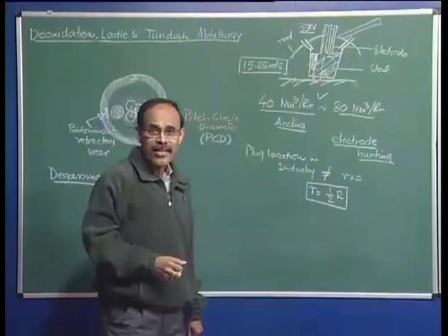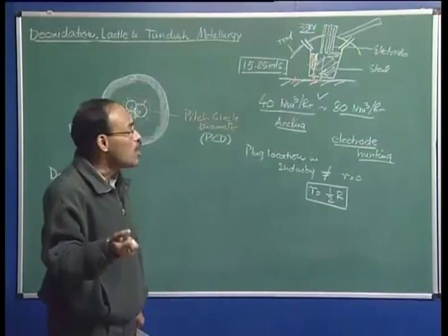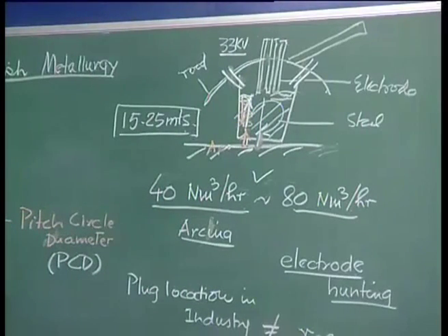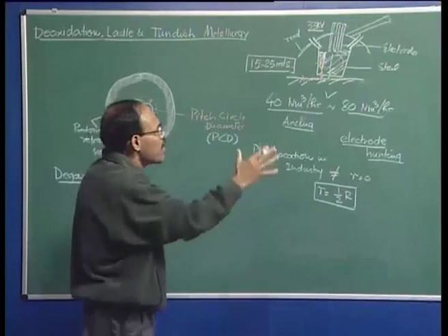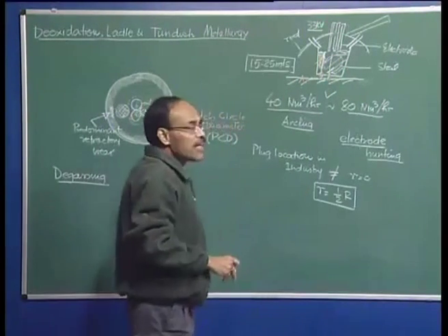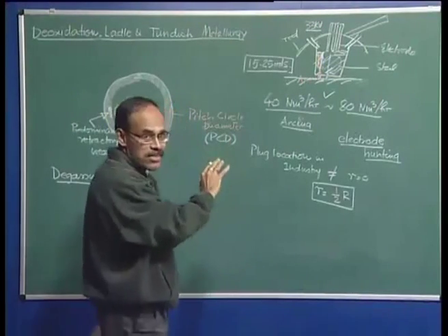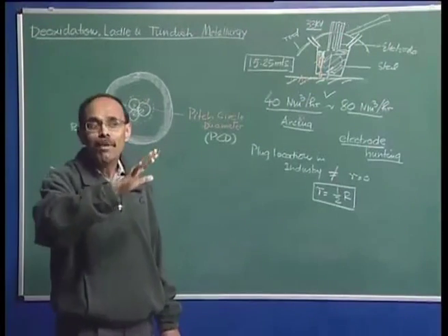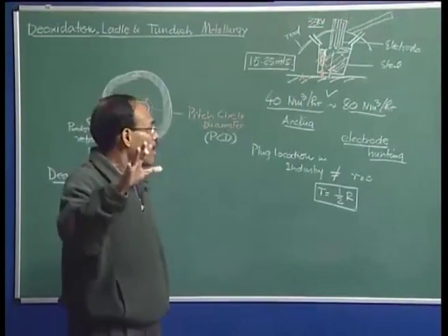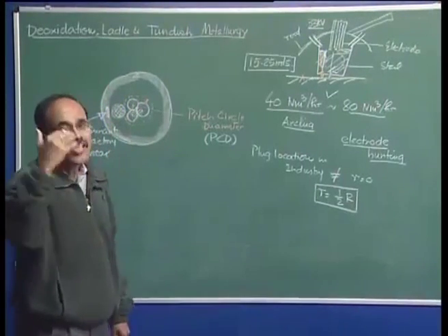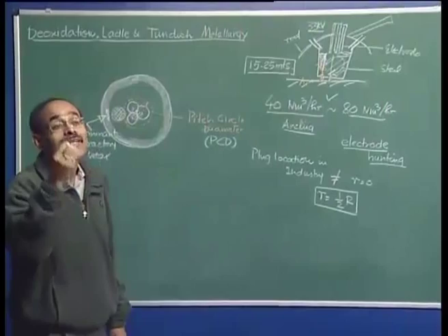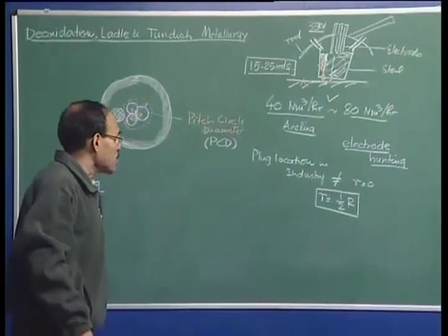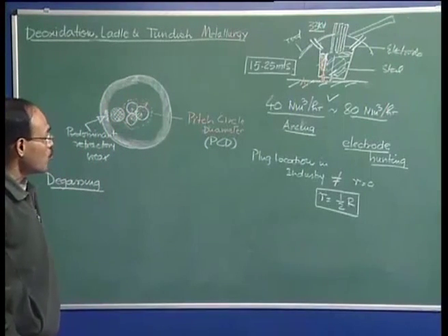The lime may be hygroscopic in nature, being hygroscopic it can contain a lot of moisture. So, carbon, silicon, manganese or sulfur, phosphorus and other alloying additions, niobium, titanium, etc. may be right, but at this particular stage the material may still contain some dissolved gases. And once we eliminate dissolved gases, that means the composition of the steel in the ladle is going to be perfect, its temperature is going to be nearly right, okay. And at the same time, towards the later part of ladle treatment we only have to ensure the level of cleanliness in the melt, and once we have addressed that point, we can go forward and cast the steel through a steelmaking tundish, ladle, mold assembly.